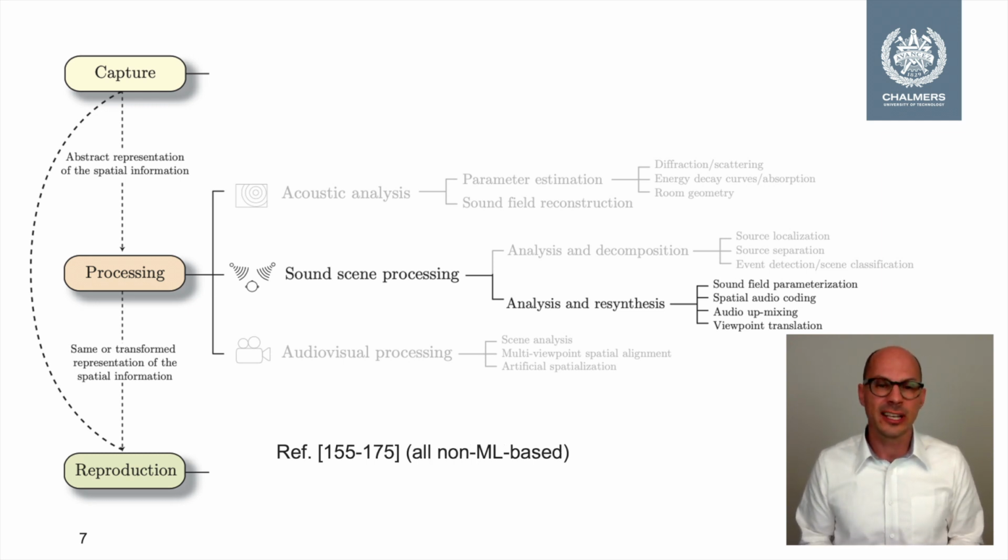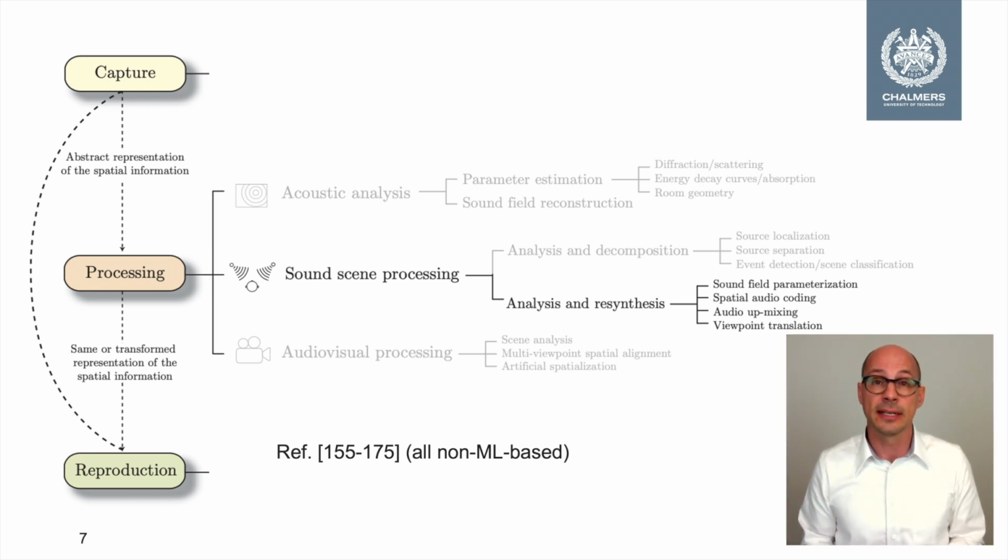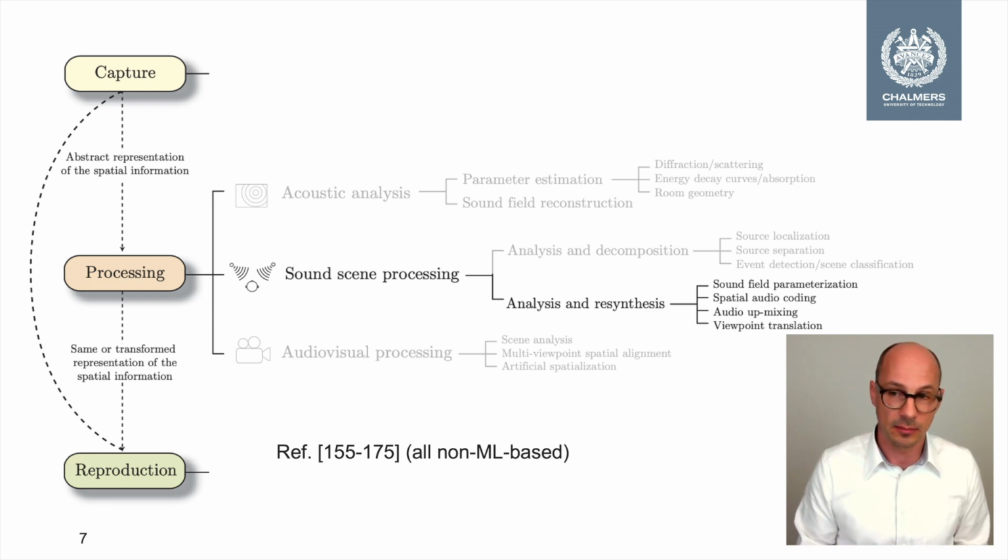Lastly, viewpoint translation, which is applied particularly in the context of binaural reproduction, has gained momentum recently. It performs viewpoint translation either by means of manipulating a spherical harmonic representation of a sound scene, which is obtained from a single microphone array recording, or by cleverly parameterizing and interpolating between array recordings that were performed at different locations. All this is based on conventional signal processing.